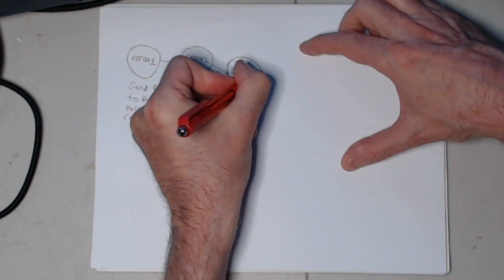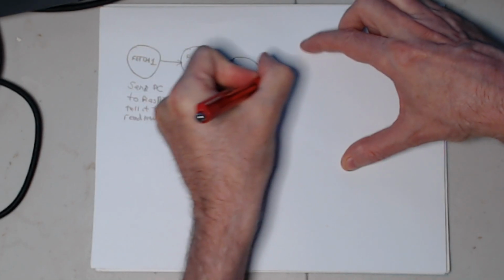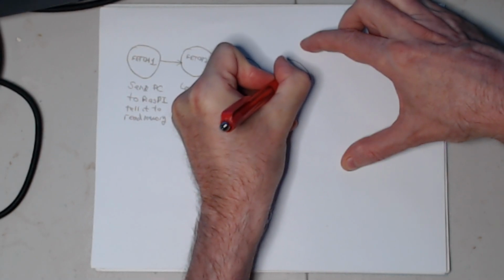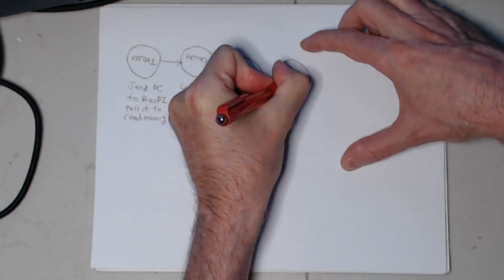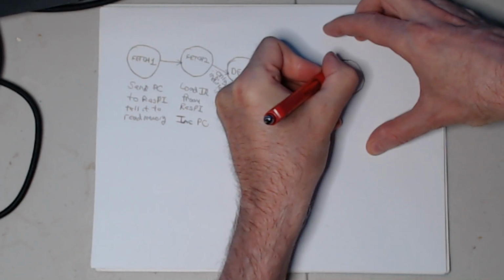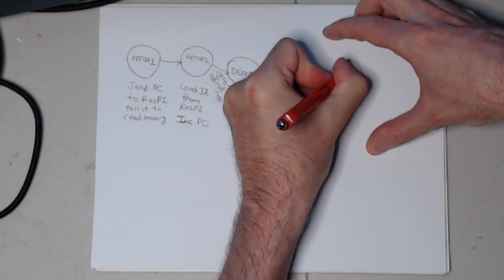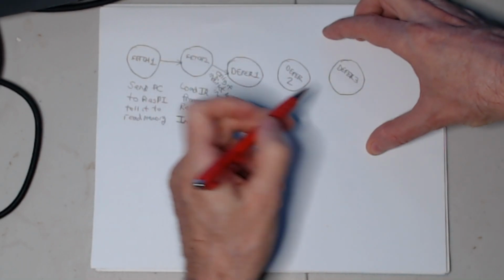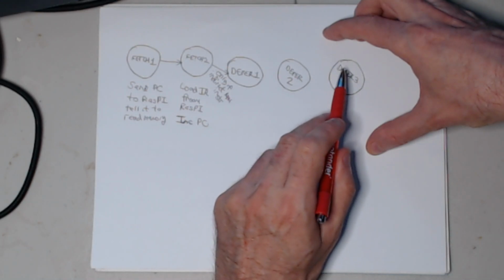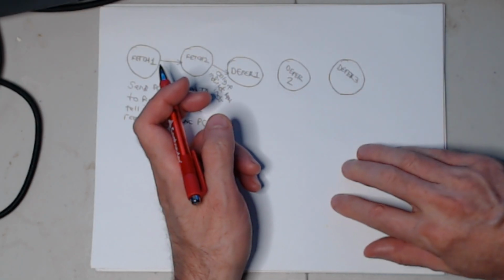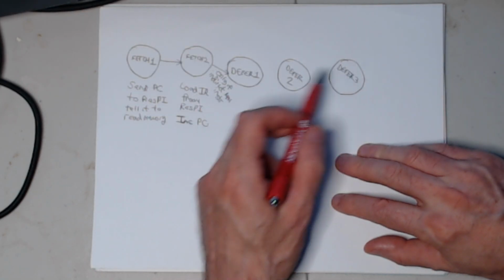So we're going to have defer 1, defer 2, and defer 3. We might need defer 3. I don't know if we're going to need it yet or not. We'll have to figure that out. When are we going to need defer 3? Because it might possibly be a read, modify, write. Okay, so that takes up to 3 cycles: defer 1, 2, and 3.